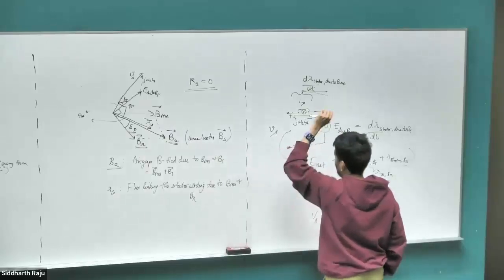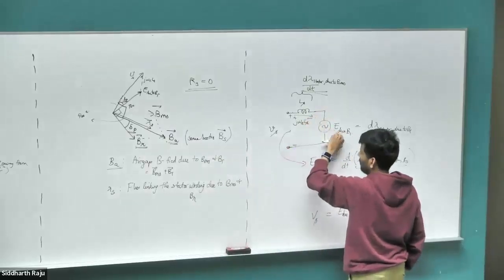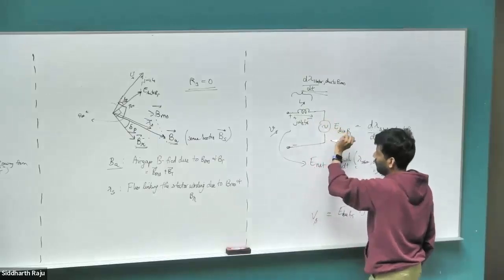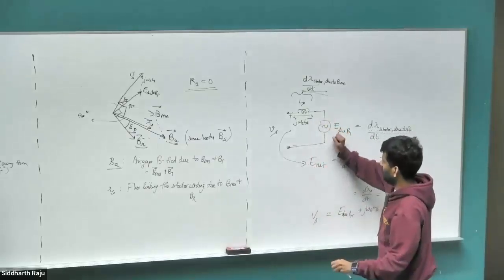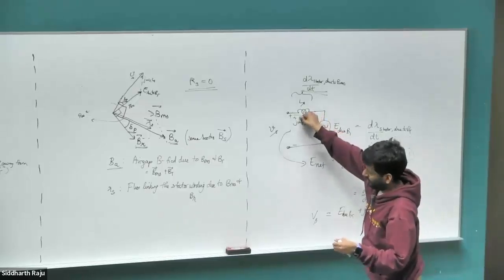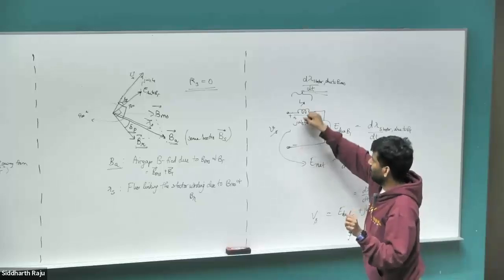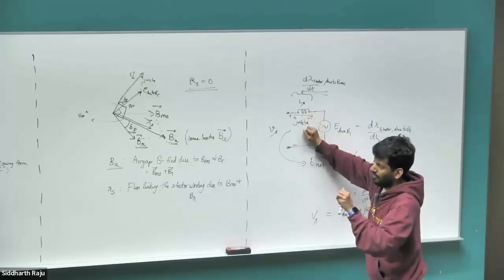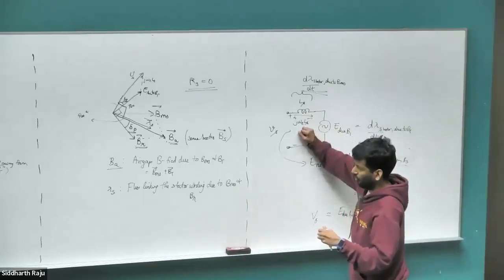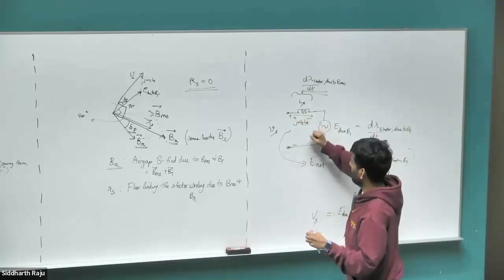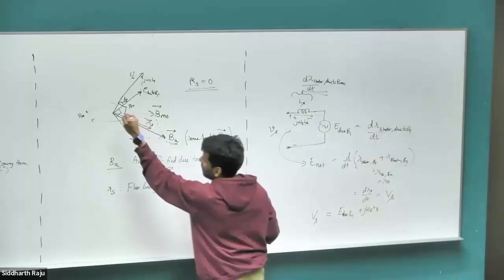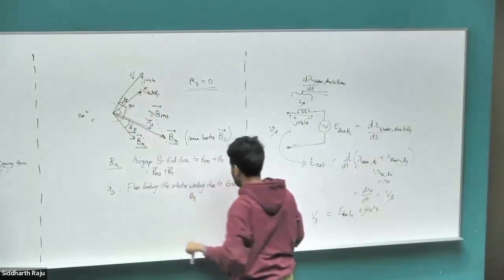There's one more point of confusion: whether back EMF is only this term. No, not at all. This is the back EMF because the rotor is rotating and the rotational motion creates an EMF, and that we typically call the back EMF. The voltage that's induced across this winding is also an EMF. It's not back EMF, but it's an EMF because it's created by the varying magnetic field due to the stator currents. It's an induced voltage. And the sum of these two voltages is the net EMF that develops across the stator coils, which would be this term plus this term.